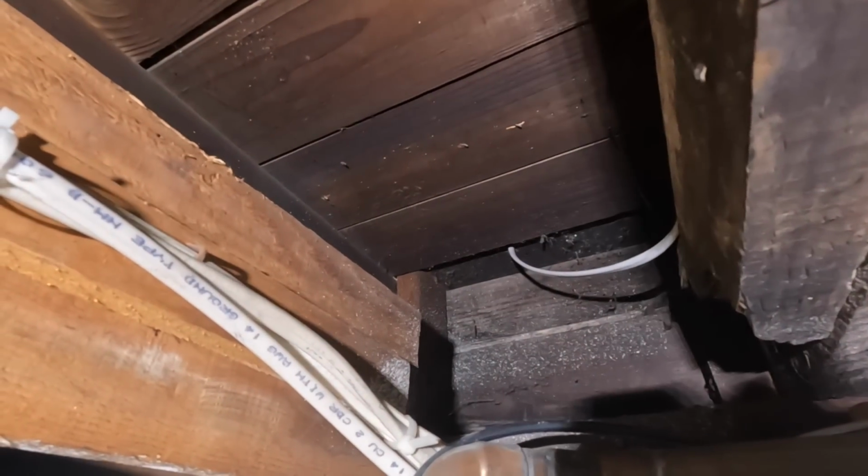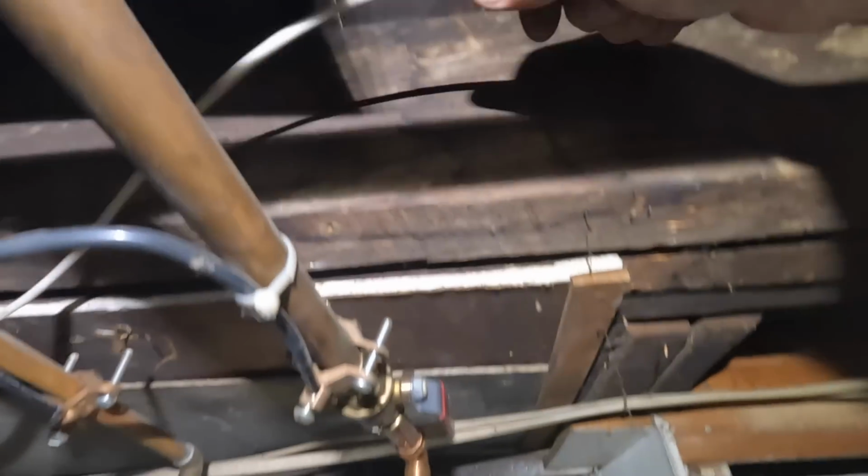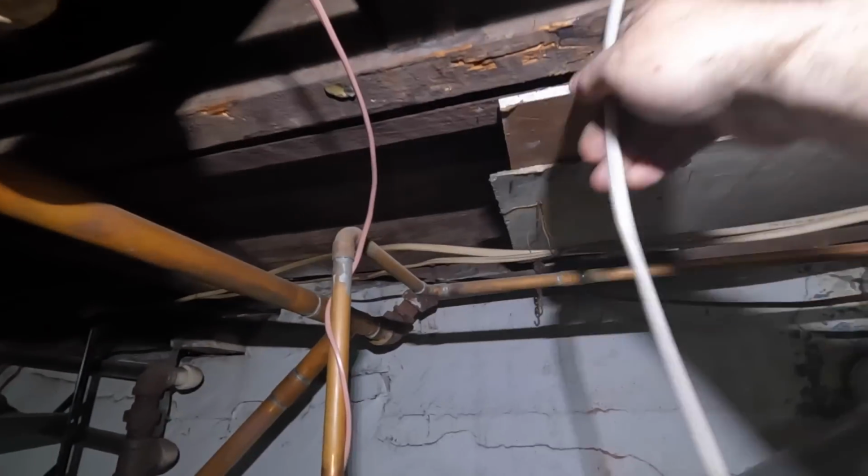Okay, so I pushed the wire down from up top, and it runs along this board and goes through one of the old holes where the tube used to be. And as you can see, I'm extending this through the circuit. I'll come back with my stapler to tack this cable up. But what I'm going to do is put a round box right here, a nail-on box, and put a pull chain light.